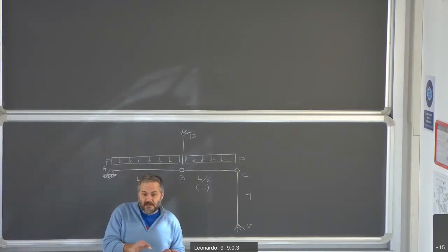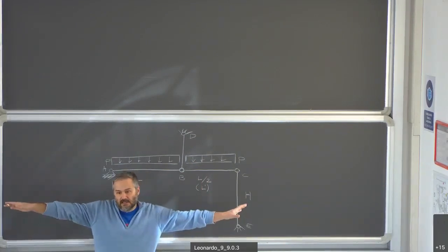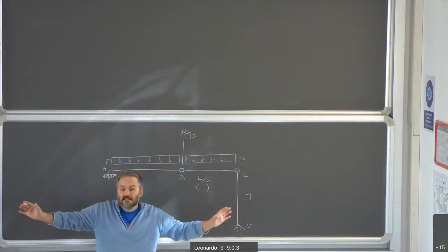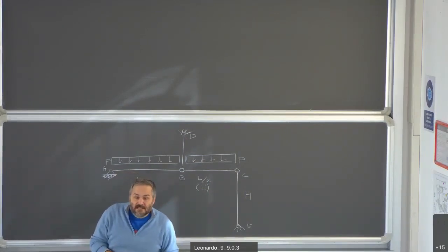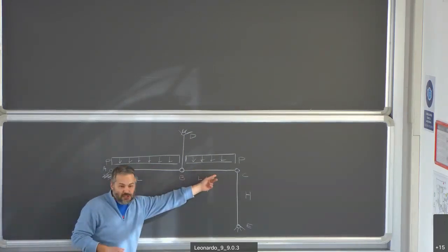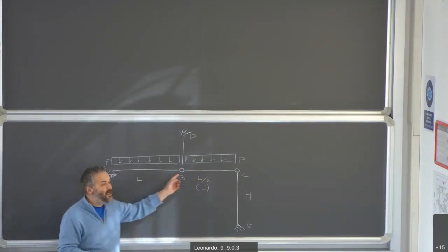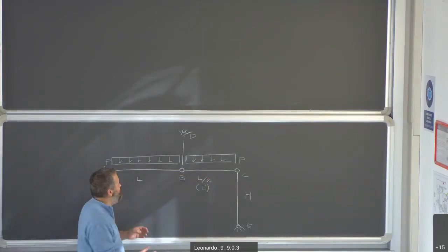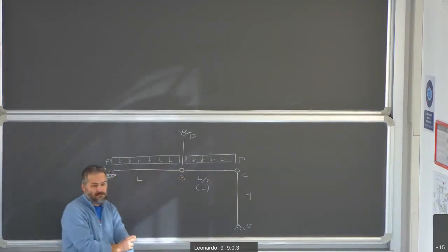As regards bending moment and shear, if you have a hinge and a hinge, no matter what there is on the outside, it's a simply supported beam, okay? Which basically means that to determine the bending moment and the shear in these two beams, I don't need to know everything about the structure. I just need to focus on what's happening on the beam.